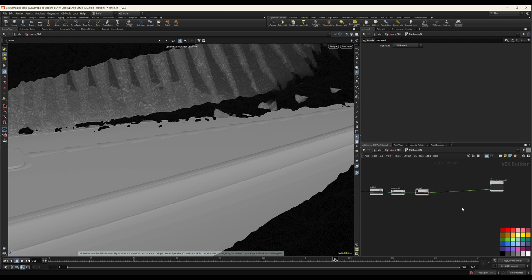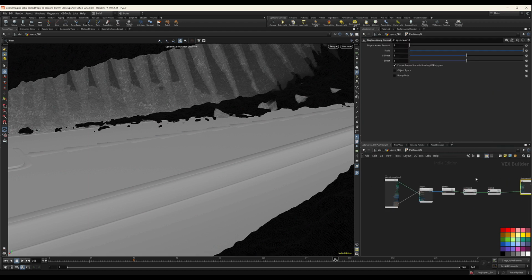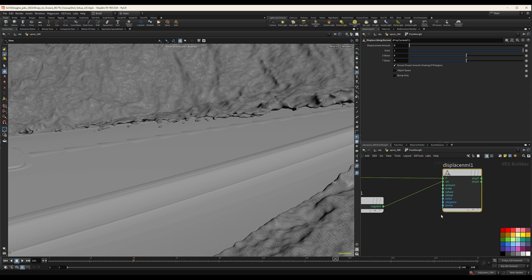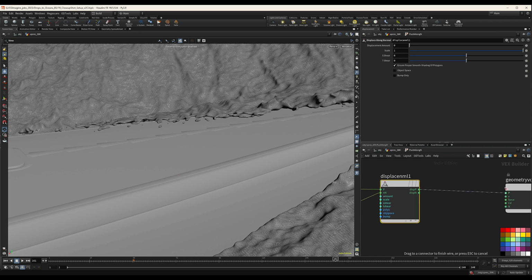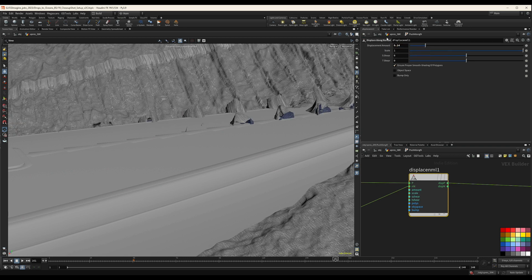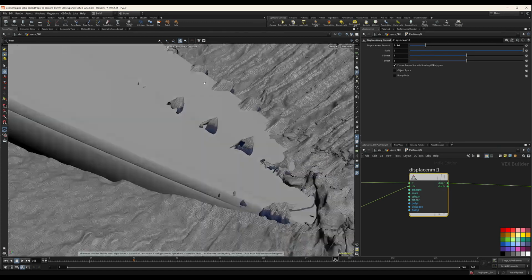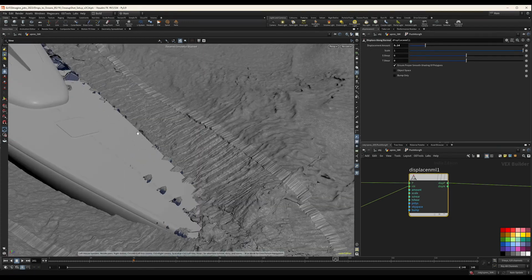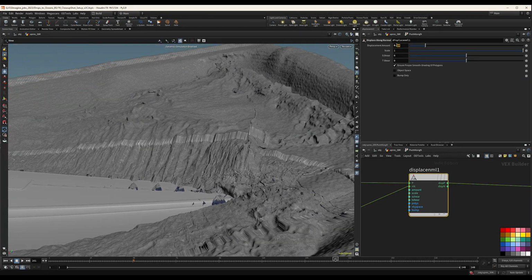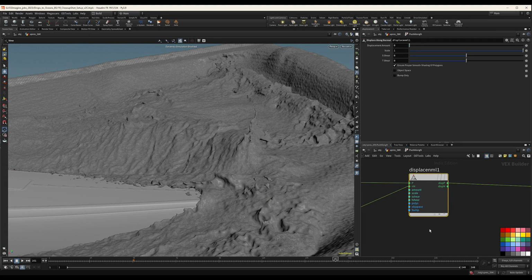And if I do a displace along normal, and I grab the original position, and grab this normal that we just created, and plug that into the position, now if I come to the displacement amount, like 0.14, you see it pushed everything all the way to here. It pushed down based on this normal. So yeah, let me keep it like that.